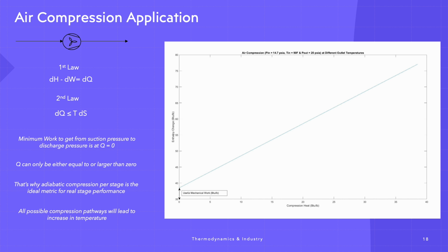Yeah, absolutely. That's pretty much, in a nutshell, where the entropy is coming from. In a perfect world, every joule I'm spending in the compressor should be gaining potential energy for the gas. But unfortunately, in reality, that's happening inside the casing. That's static, it's zero, and the gas basically has to overcome friction. And on top of this, the rotor is moving at a whole different speed.